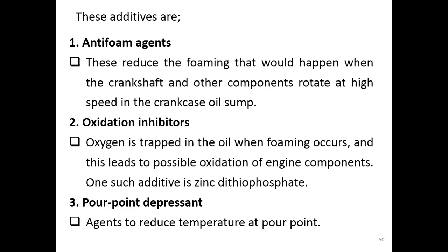So we need to add an additive to inhibit the oxidation. Such an additive is called zinc dithiophosphate. In the lubrication oil, we add this additive to prevent any oxidation, so rust cannot happen to our engine components.